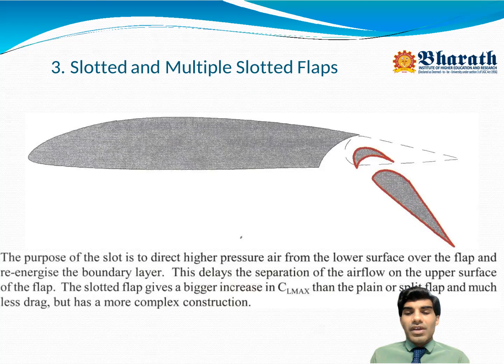So as you can see in the figure itself, it has different multiple slotted flaps. It is difficult to construct and increases the cost also, but it gives more lift compared to the split and plain flaps and generates less drag.